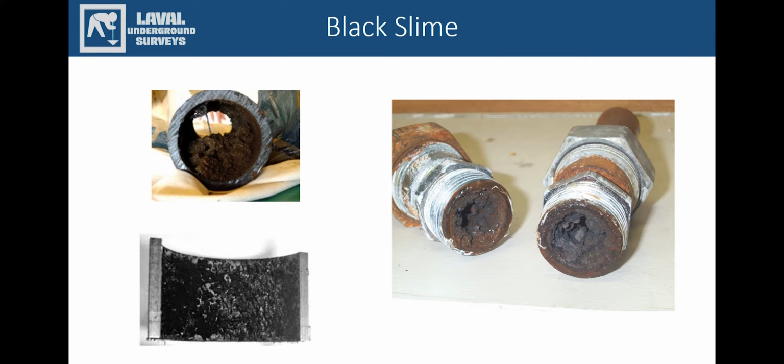Corrosivity is most commonly associated with the black slime due to initiation of electrolytic corrosion by the hydrogen sulfide generated by the microorganisms. Black slime could also include iron-related bacteria with manganese in its biofilm. Because the iron bacteria is sticky in nature, it often incorporates other things. This can look like black slime when it's really manganese that's stuck inside, changing the color from red and orange to dark gray and black. Manganese is a mineral, so it's important when cleaning to understand that you're treating biofouling and mineral scaling when treating black slime.